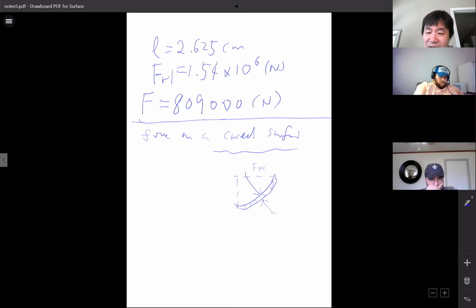If we can find the force on these plane surfaces, then maybe the overall force is related to those two components. Maybe not exactly the same, but related. Maybe we have a hope to do it easier without using integration, because in the plane surface you don't need to do integration, right? That's the logic. So let's cut into these two planes, vertical and horizontal.